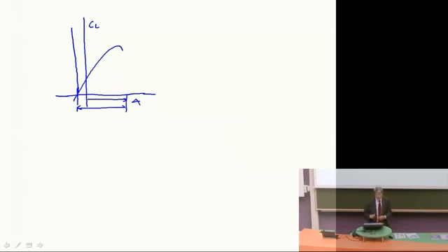In this way, when you get a point on the curve and you get the absolute angle of attack and the lift, you automatically have the steepness of the curve. By just dividing the lift coefficient by the absolute angle of attack, you automatically get your a, your dCL/dalpha.